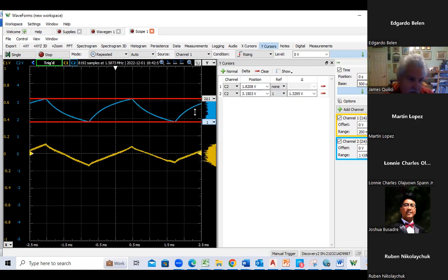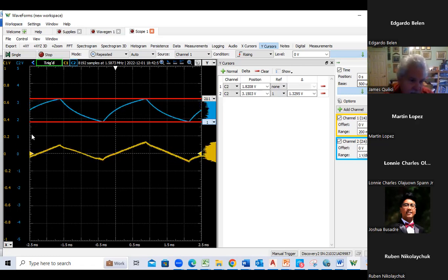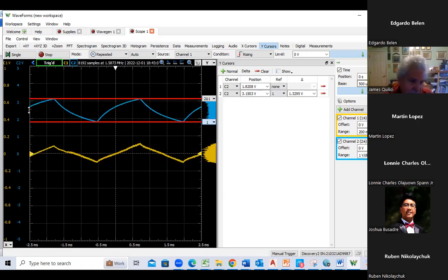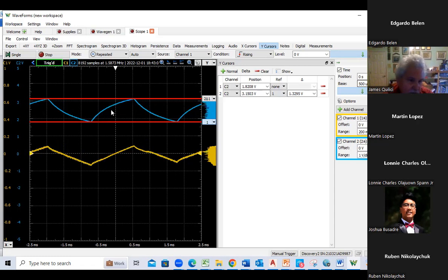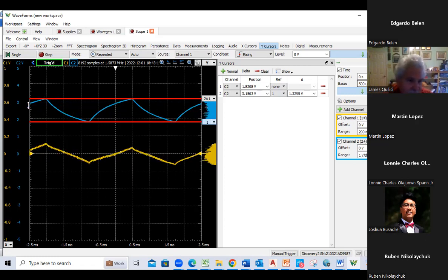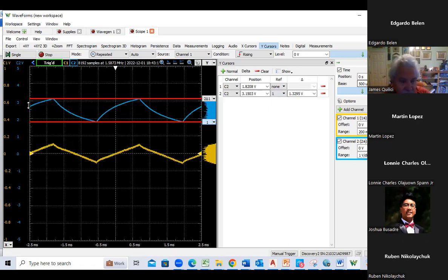Again, what I'm looking for on mine is ideally that this thing is oscillating right on a DC offset of either 2.5 or 3 volts. That'll give you the most dynamic range. That's basically your collector voltage there. And then your base should probably be somewhere on the order of 1.3 volts to 1.6 volts for this thing to operate well.